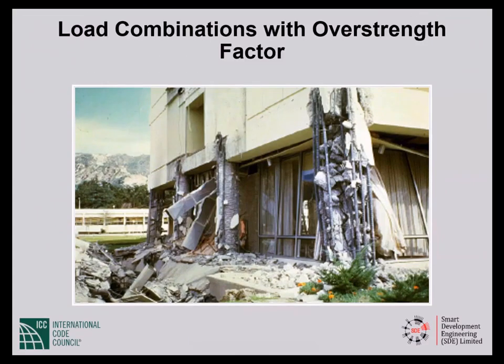This is a by now famous picture. This was the Olive View Memorial Hospital after the 1971 San Fernando earthquake. You see the bottom story has columns, and then the shear walls start. Those columns, back in those days, where there was no difference between a California column and a Chicago column, have plenty of longitudinal reinforcement, hardly any transverse reinforcement. Tie spacing was 12 or 14 inches, no 135-degree hooks, no cross ties.